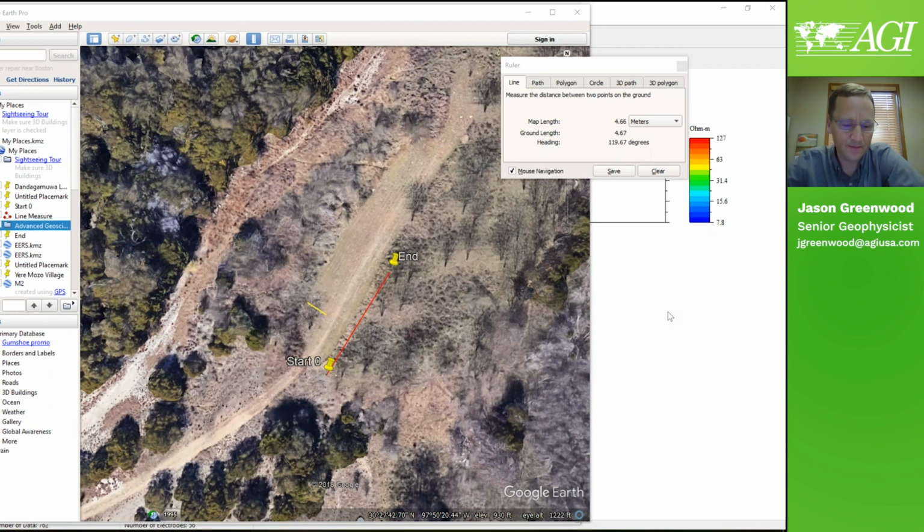is very little impact. So there's a lot of data collected parallel to roads, which are concrete, and there's no issue there. Sometimes they even run on a crack or an expansion joint. They put the electrode through that into the subbase, and there's ways of coupling to the subbase through concrete that has worked quite well. And if you happen to hit rebar, you can even put a plastic pipe or sleeve of some kind to insulate the electrode from that. So there are case histories like that.